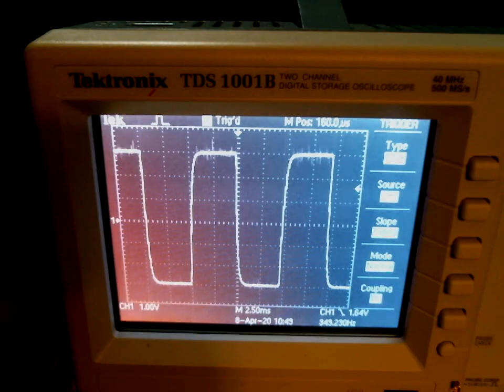So now I've got my function generator's amplitude turned up a little bit to help me see things better. So it's a total height of 6 squares when the exponential decay starts out. And just like before with the known capacitance, I'm going to go ahead and zoom in on the time base.